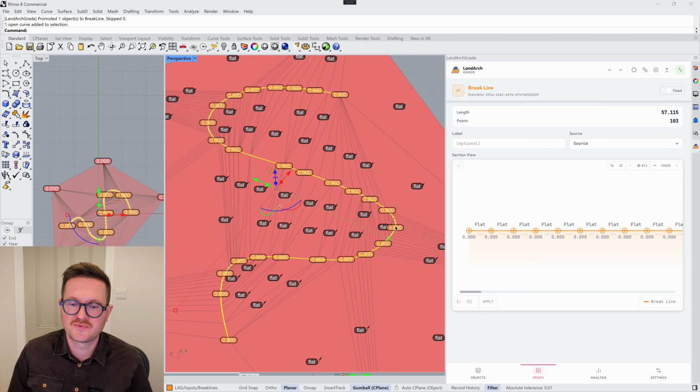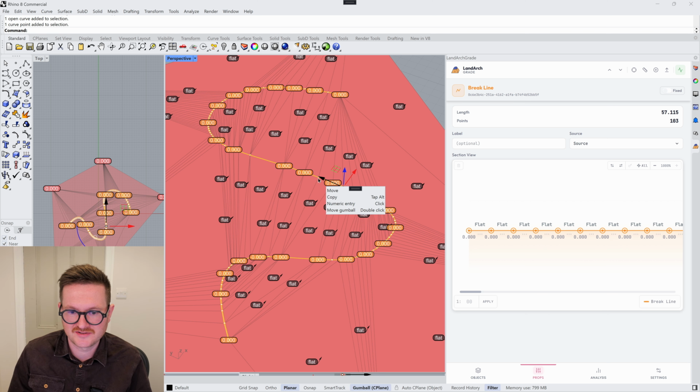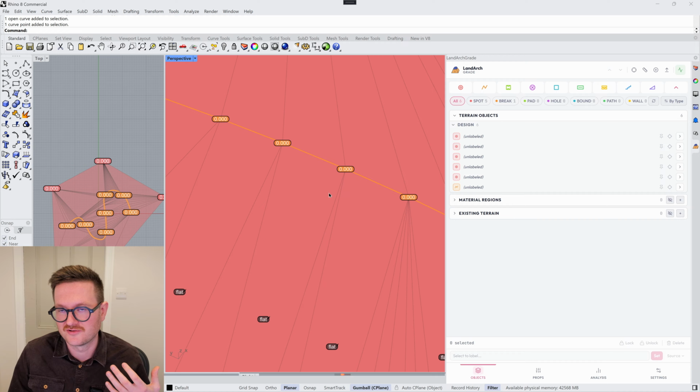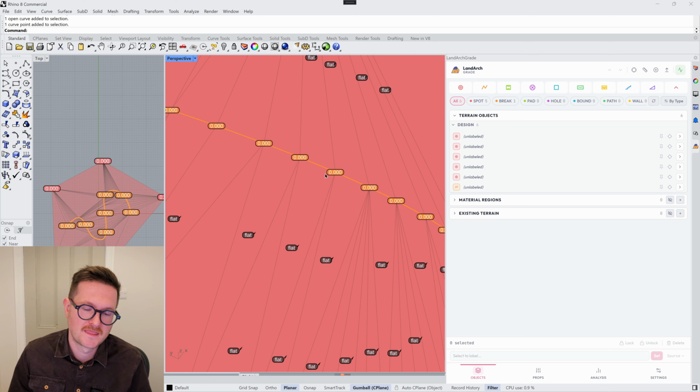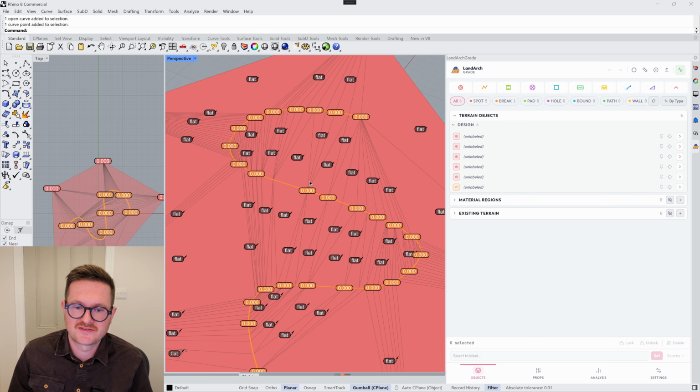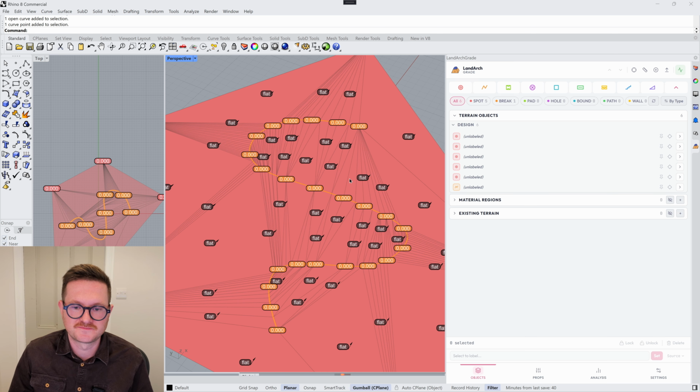So if there's too many points on screen as there are now, you can see this point here and this point here don't actually have a dot height, but if we zoom in, those dots come into view. So this is all user configurable. If you want less information on your screen, just increase the aggressiveness of that cull as well.